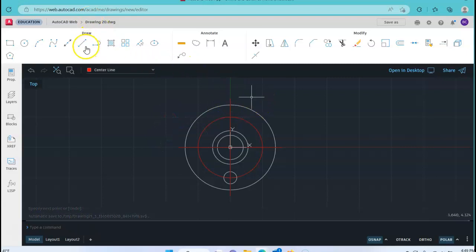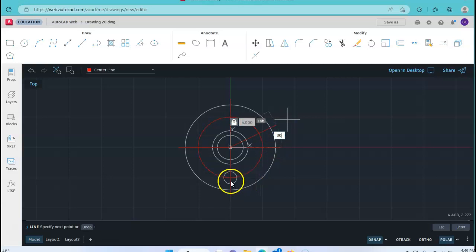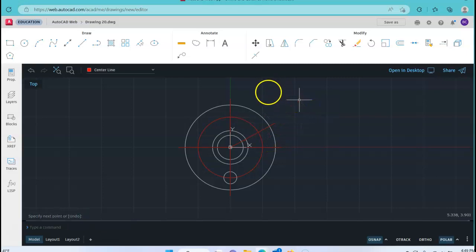And now I can come back in with the lines. I know at this point I can create a line going up this way. We'll do a 4-inch line, tab over. This is going to be 30 degrees. Why 30? Well, 90 degrees plus 30 is 120. So, and I'll hit enter. Right click, confirm to get out.